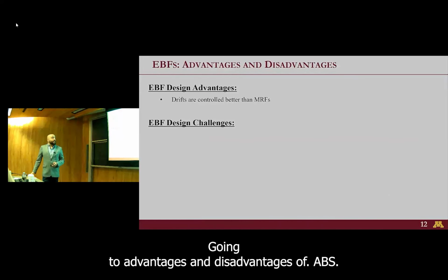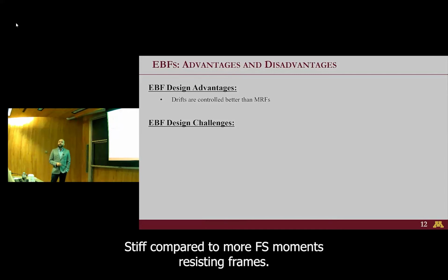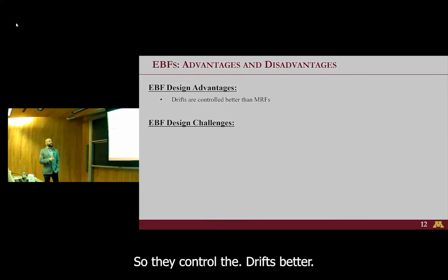Going to advantages and disadvantages of EBFs. The main advantages are that they're more stiff compared to MRFs, moment resisting frames, so they control the drifts better.